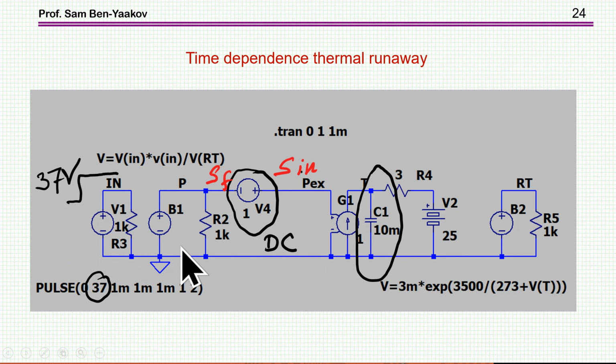And then what will happen is, the power is due to the voltage and the resistance at this particular time, at the beginning, say, and then as the temperature goes up, the resistance goes down, and therefore the power goes up, and then it depends on the time constant of the system. If this capacitance is very, very large, then the temperature does not go up very fast, so it will take a longer time. But eventually, in the case of instability, there'll be a runaway.